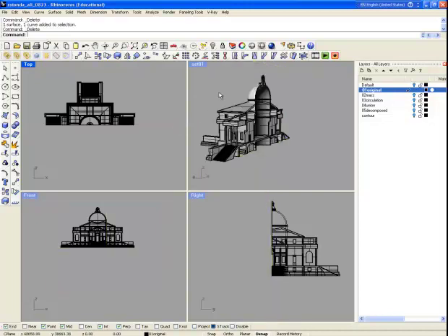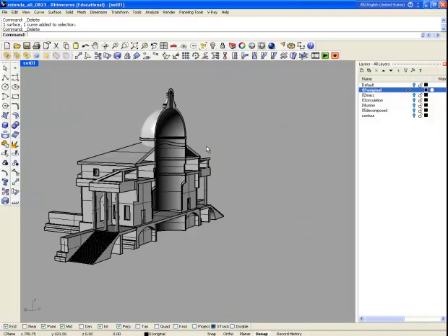Okay, and then I don't need to have this section cutting surface anymore. Delete that also. And then now I'm going back to the perspective view, and before you get into the next process, what do you need to do? You need to fix or save a named view. Then whenever you want to go back, you can just fix the view and fix the perspective angle in order to make some synchronization between your section hatch and the outline of the section model.